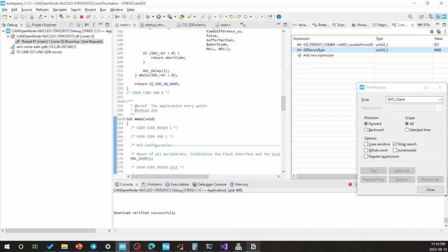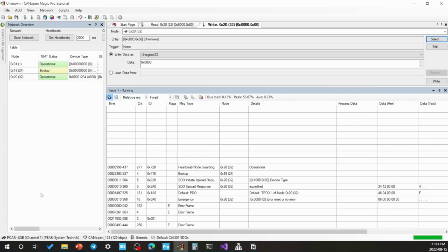You know the problem in my network is that this STM32 F0 that I have, when you reset it, the transmit pin will float for a while, so it will transmit some random errors, and that basically puts the STM32 G0 in error mode, and I don't have the code for error handling for that one. You should have that actually, but then you just reset the microcontroller, and then you can read the values, and CANopen will work as expected.